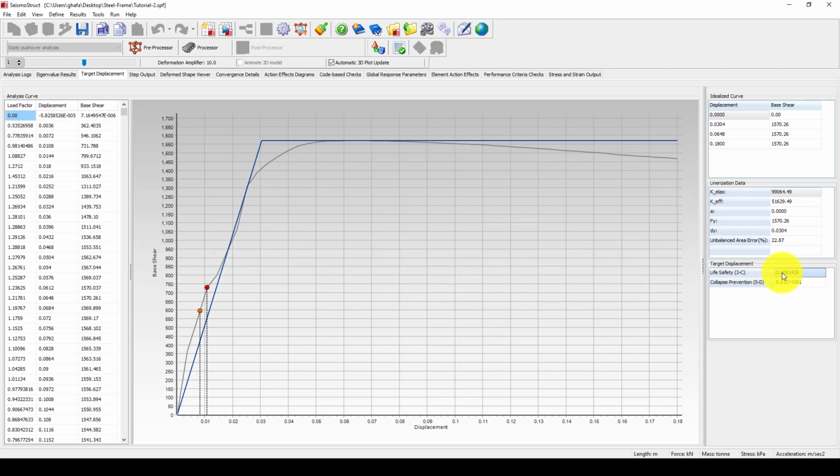Now here, the data means the life safety is already reached and the collapse prevention target is already reached. You can see here is 0.8, and we already have here. This is the life safety, so the structure is here. This point and this point is collapse prevention, so it will start to collapse, because in this area mostly the infill wall will be damaged significantly. But this one is the reinforcement. So the reinforcement will also reach the maximum or collapse prevention after this displacement.